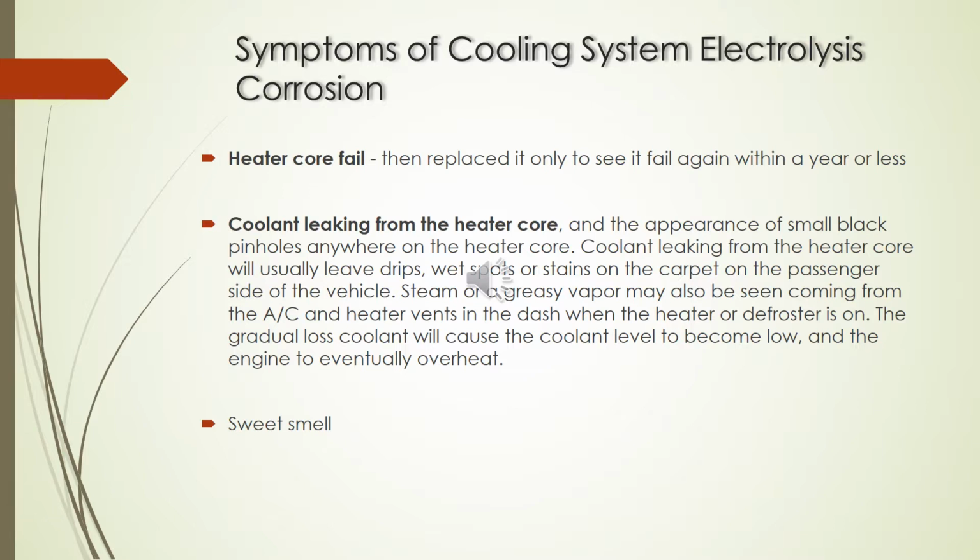Another symptom is the coolant leaking from the heater core. Once the coolant starts leaking from the heater core, it leaves some drips, wet spots, or stains on the carpet of the passenger side. Another prominent sign is the sweet smell once you turn on the AC.